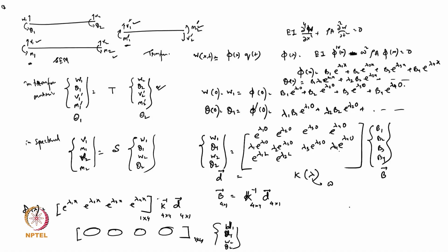If you want to also see, there we are assuming some variation. For example, if we are taking a bar, we have u1, this is u2, and we assume a linear variation. So at x distance, what will be my value? u(x) will be u1 plus (u2 minus u1) divided by L, sorry, u1 minus u2 divided by L into x. That is my function for a particular point.